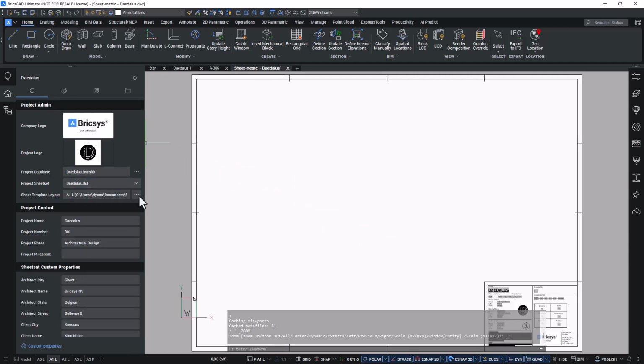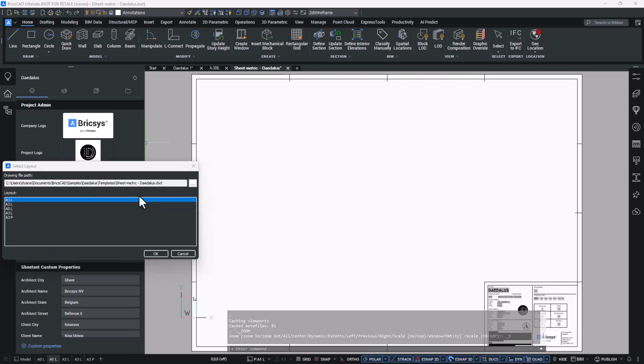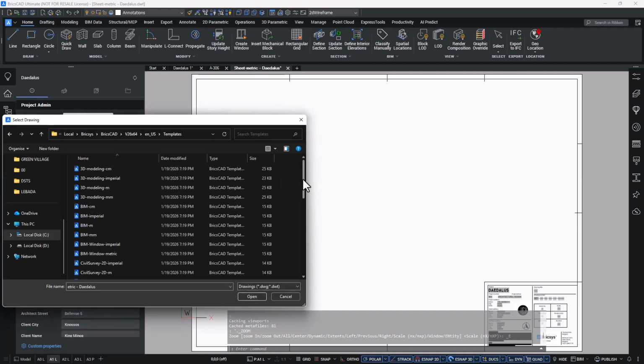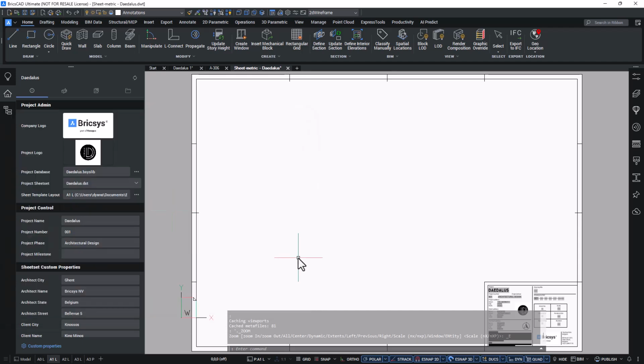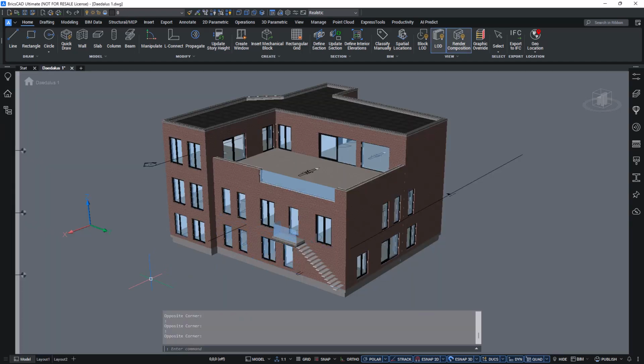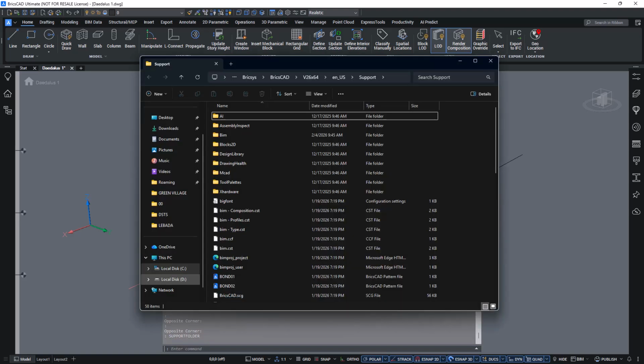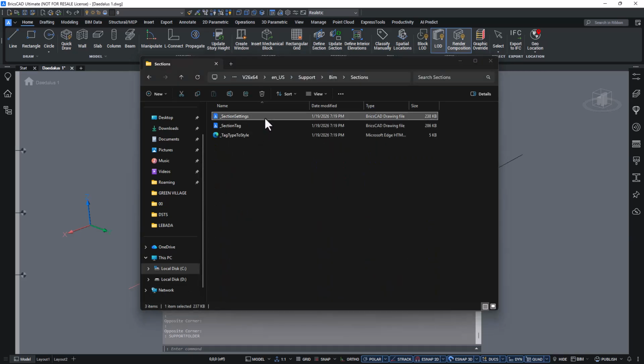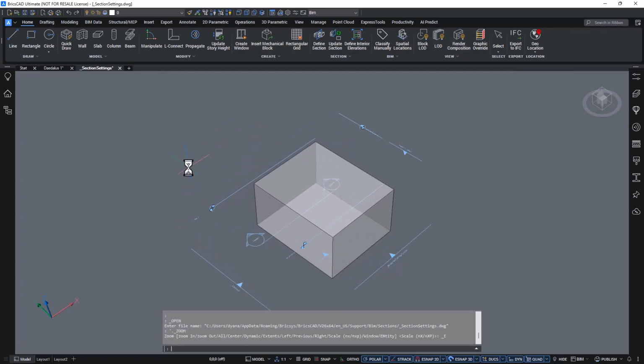Launch the BEdit command to choose the callouts or the section tracker block you want to edit. Launch the Section Plane Settings command and the Drawing Explorer will be displayed with the Section Planes category opened. This category reports the number of section planes defined in the drawing. Select the type of section you want to edit and make the desired changes.